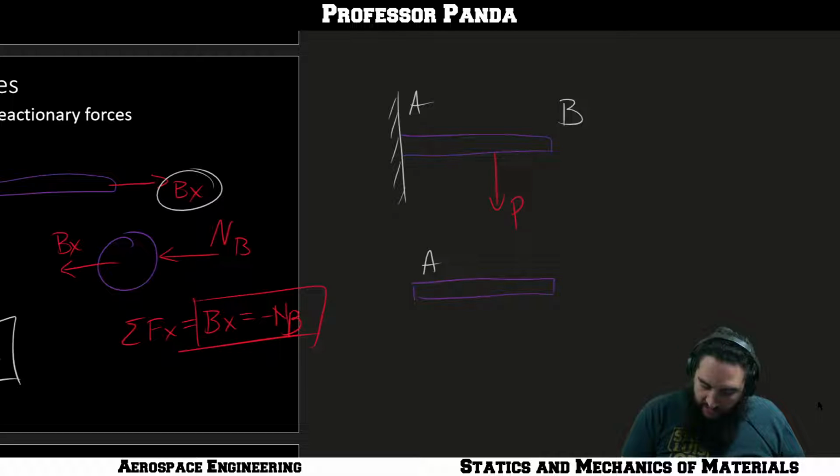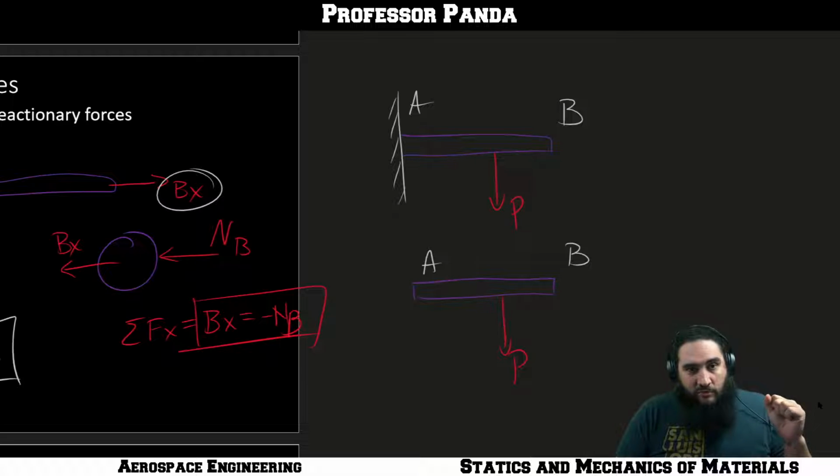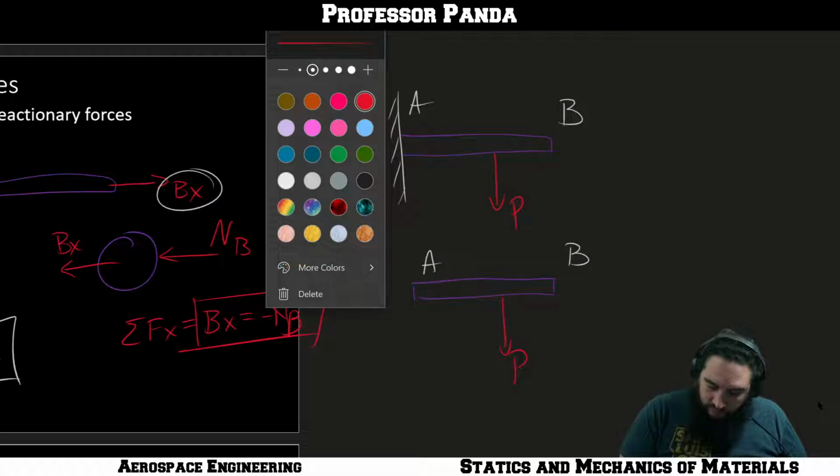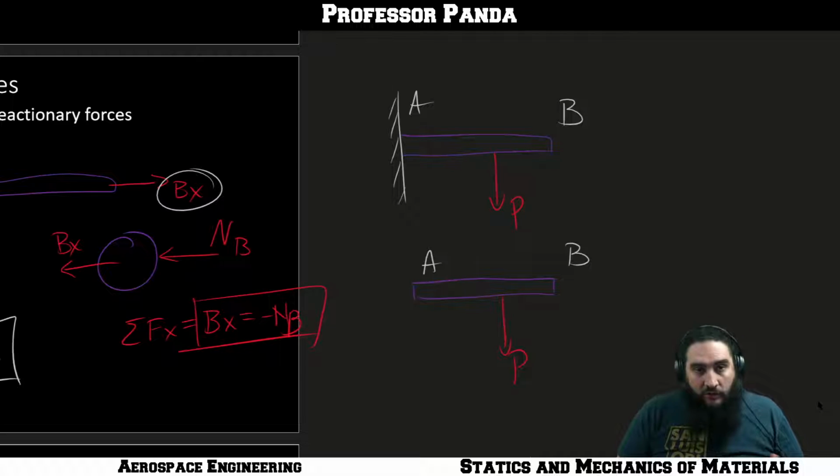Go ahead and label these. Copy down my externally applied load, P. And at Bravo, we have nothing. It's a free end. This is like, you know, you go to a pizza shop and there's a sign that sticks out of the wall. There's nothing there. All of the reaction forces that are keeping this bar in equilibrium, this beam, are going to happen at A, the building,